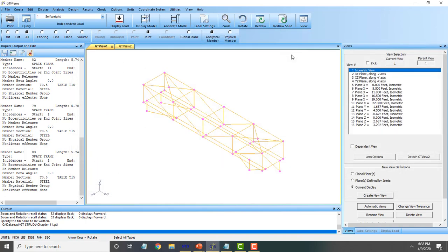So what we're going to do now is add a lateral load of 0.0345 kips along the global z direction. I'm on page number 120 of the PDF document, or chapter number 13 on Kindle or Amazon. If you have downloaded the book, first we need to create a new load case.